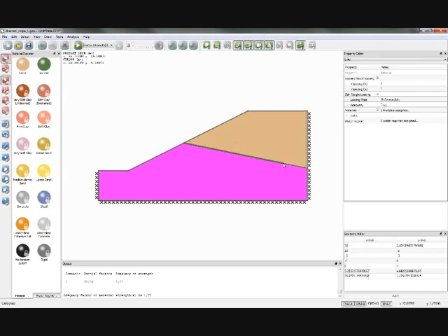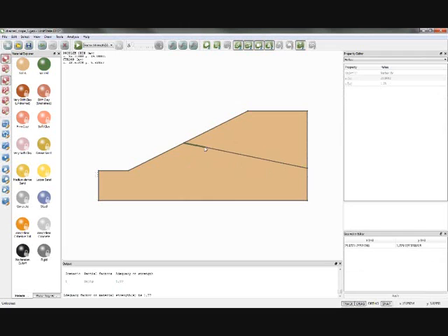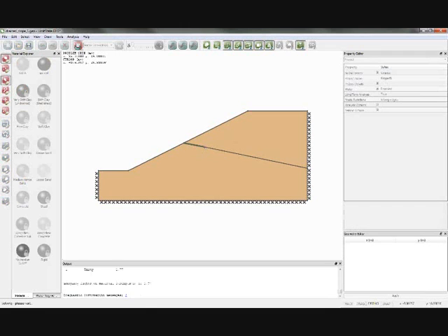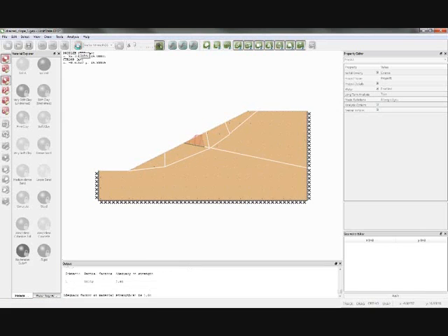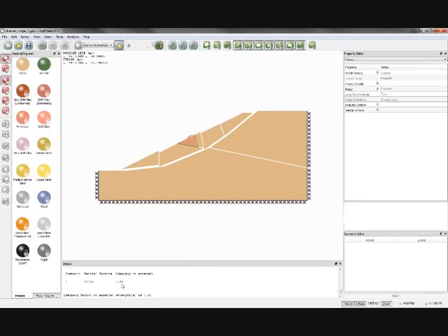And as before, if I shorten that down too much, then of course that's going to become a rather ineffectual nail, and we will revert back to our original type of failure mode, which will come out to around about 1.63. It's changed slightly because adding that nail has slightly changed the distribution of nodes in the problem.